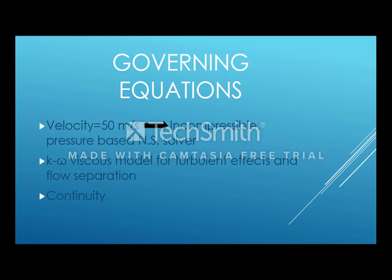Turbulence was a variable of interest. The k-omega viscous model was used to take into account these effects and flow separation. As with all other flow problems, continuity was also included.